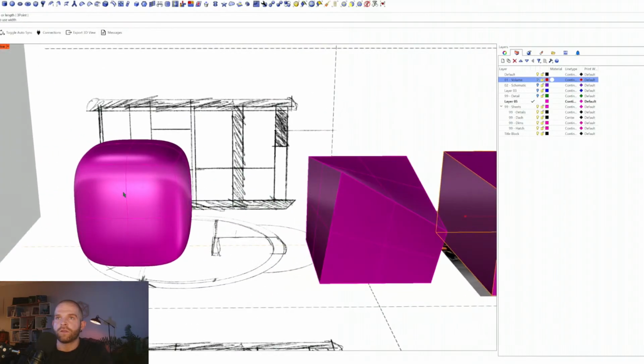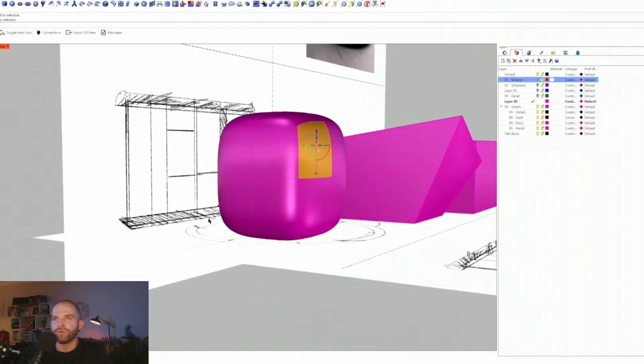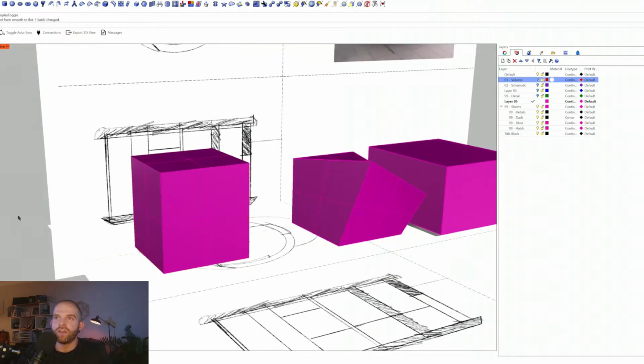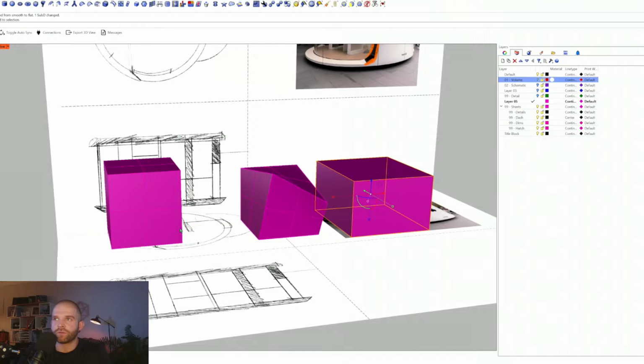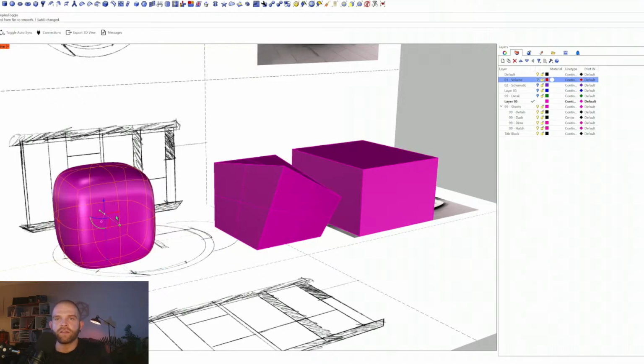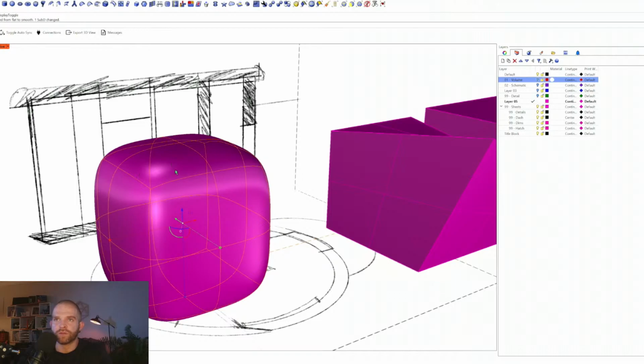Okay. So this is just a face of 1, or a division of 1, which looks like for a SubD it splits into 2 faces anyway. So if I hit tab, you'll see we're getting actually a similar cube to the one on the right for this SubD. That's because it's also a mesh, but by hitting tab, we're previewing that subdivision that's happening, which is the smoothing of these faces basically, versus no subdivision, right?